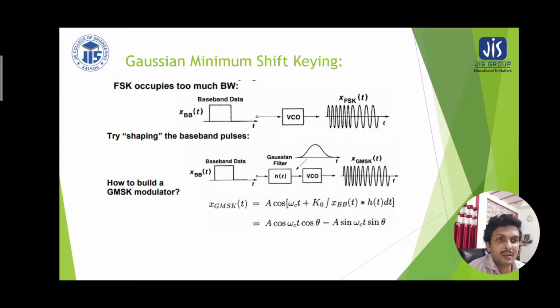but still the larger bandwidth is one of the great limitations in terms of the expense of the system, because the service provider has to spend more, and the consumer also has to spend more compared to other systems. So frequency shift keying has one disadvantage in terms of cost, but in terms of noise it is a truly robust system, because if there is an amplitude fluctuation introduced by the channel, it may be removed by introducing limiter circuits or clipper circuits, which remove the additive noise introduced into the frequency shift keying signal.